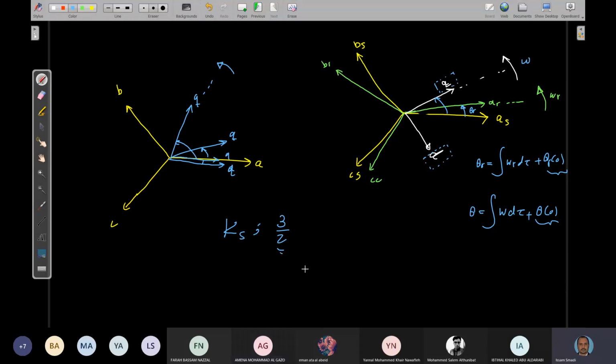Yes. Now, this one actually is correct if I'm having a balanced system. And if I'm transforming and there's no initial condition, there's no initial angle, then in the end of the day, VQ will equal to what? VM. And VD will equal to what? 0. So simply someone will say, I can regulate VD to equal 0.